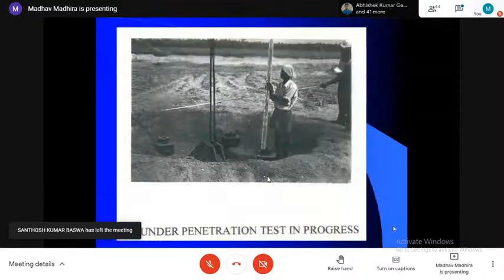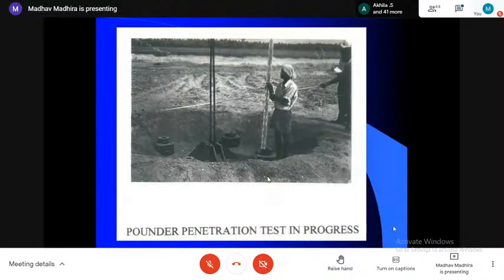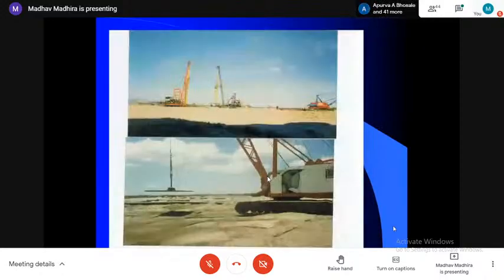And then with each blow, you find out how much the crater depth is. After some 4 or 5 blows, there will be no more densification at that point. You go to the next spot and repeat the same thing. This is how the whole process looks. And finally, you will see the ironing pass with a very large plate, something like 4 by 4 meters. You tap it on the surface so that the surface is also densified.